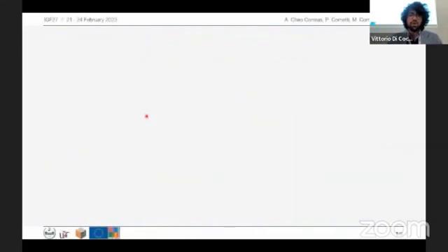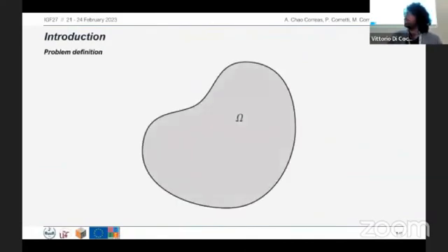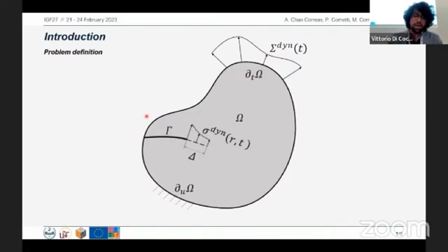For this work, we will cover the following problem. Let's imagine that we have a generic structural domain, filled with a homogeneous, isotropic, linear elastic, and brittle material that is subjected to dynamic loading and boundary conditions. This domain presents a particularity, a stress raiser, represented here by capital gamma, so that we can ensure that failure will always stem from that particularity.